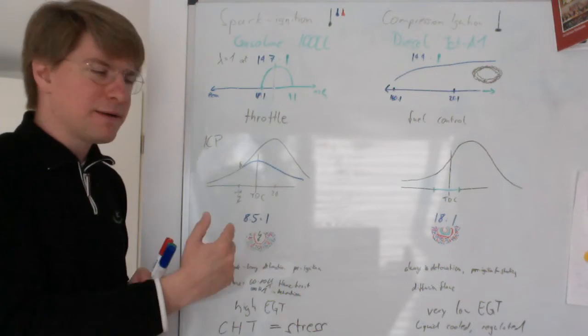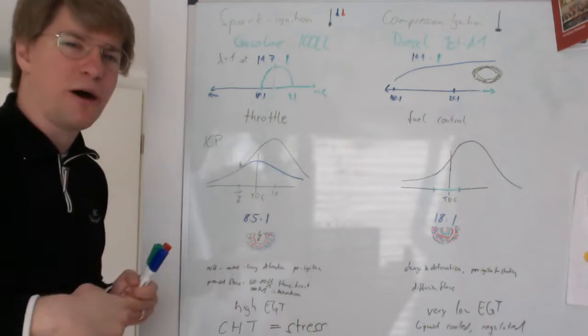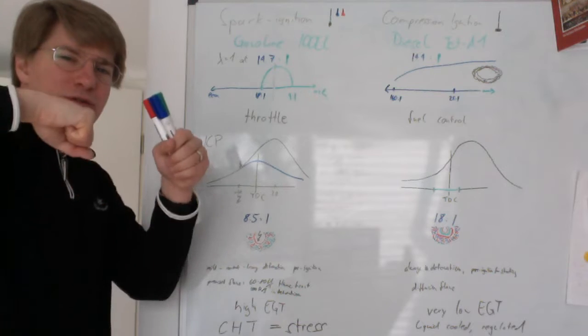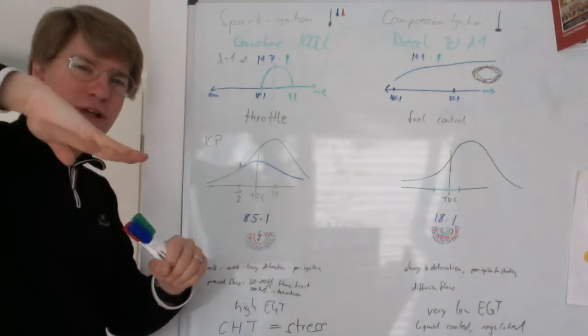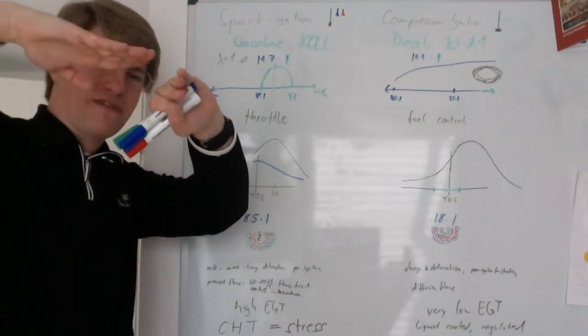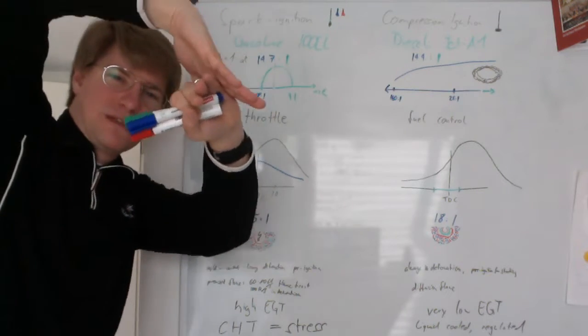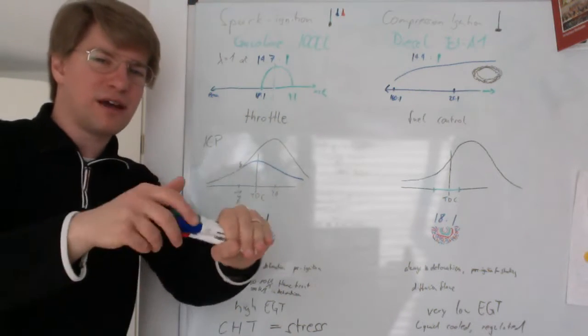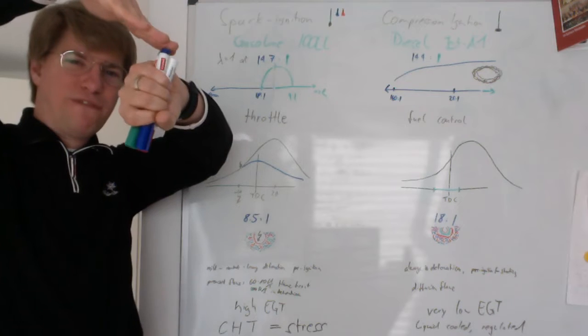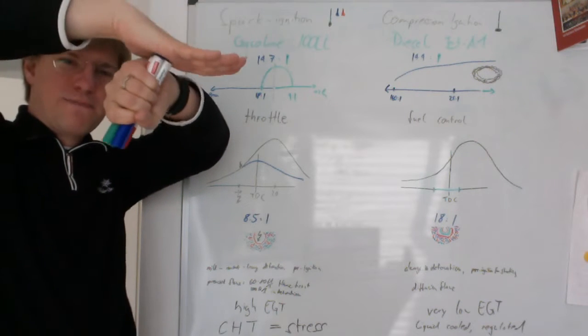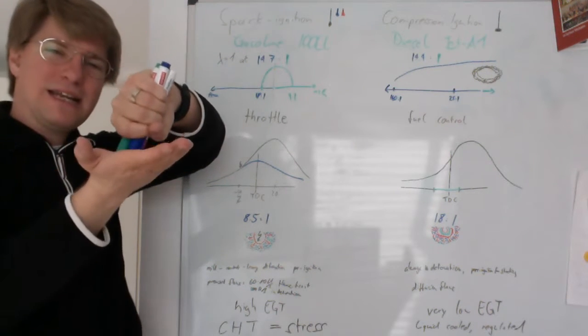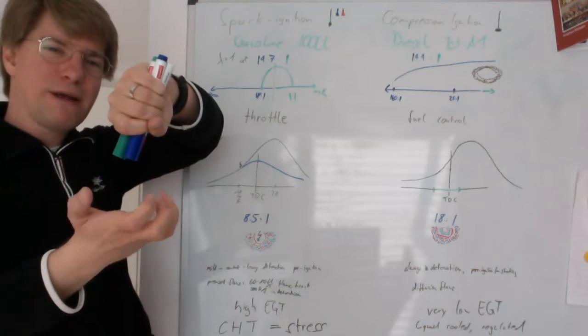And in fact, at about 20 degrees after top dead center is when we really want the highest pressure, because at this point the crankshaft is in a place where the piston pushing down actually does something. If we achieve the pressure before that, the piston pushing down merely exerts stress on the bearings in the crankcase.